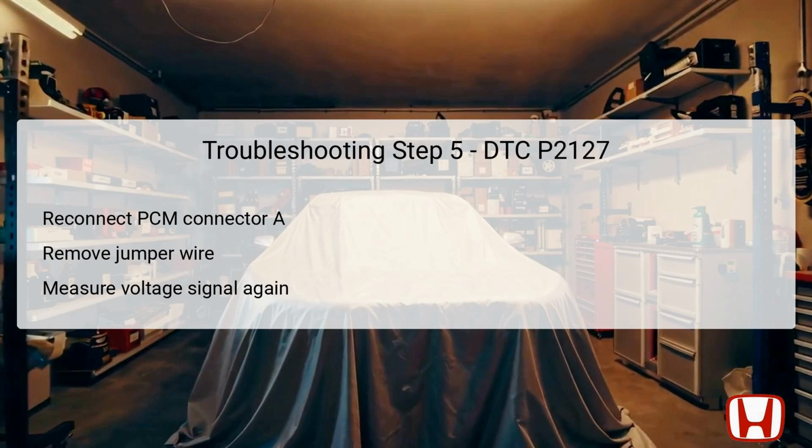Next, establish a new jumper connection between terminals A and B, which involves bridging the APP sensor 6P connector number 1 and number 3. With this configuration in place, turn the vehicle to the on mode again and check the APP sensor B readings using the HDS.